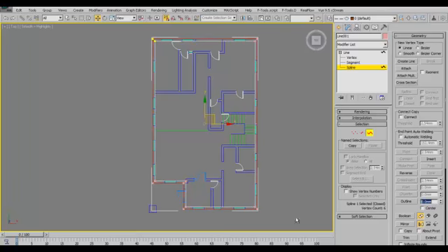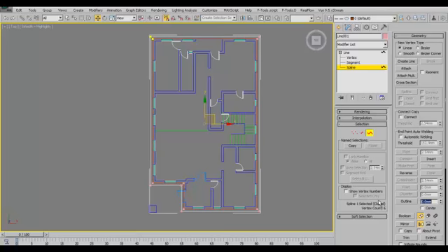If it goes the other way around, you have to undo, then use minus 225. For now we've actually flipped that part, so you can say minus 225. If we go minus 225 and it goes outside, you can just go 225 again, because that spline is still selected, and once you do that, it goes in.